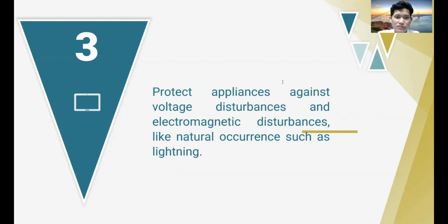When a magnetic field affects a site, such as the field created by lightning, differences in potential are created in the loops formed by various conductors and the currents flowing in the earthing system. Consequently, the earthing network is directly affected by any practical measures taken outside the building.